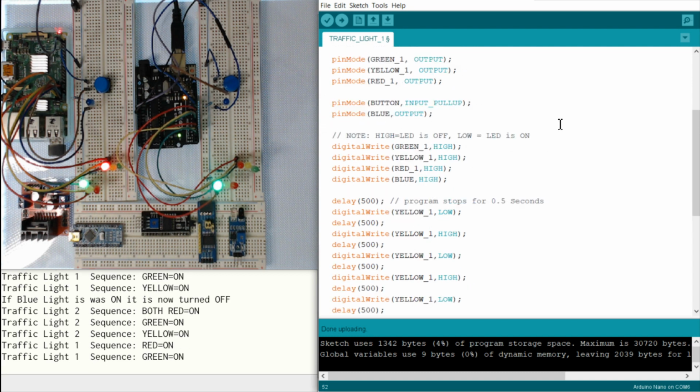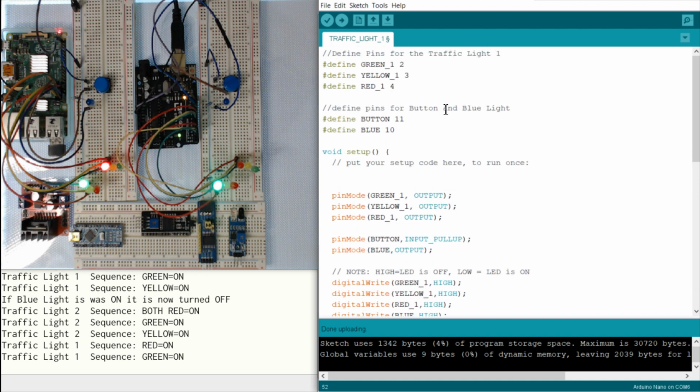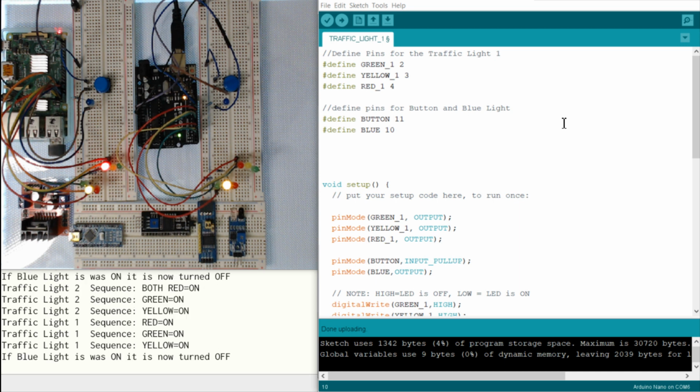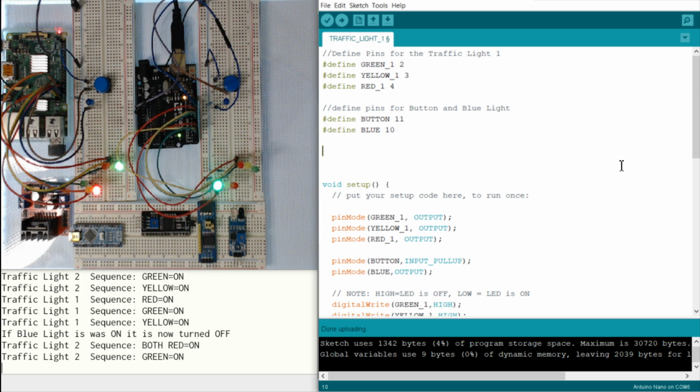So how are we going to rewrite this program to make it correct, to make it the way I would like to have it performed? Let's see if we can make it correct. We know that the button is not functioning correctly. So I'm going to use, and that's my way of working, a millis check. In the Arduino, we automatically have the millis function available.